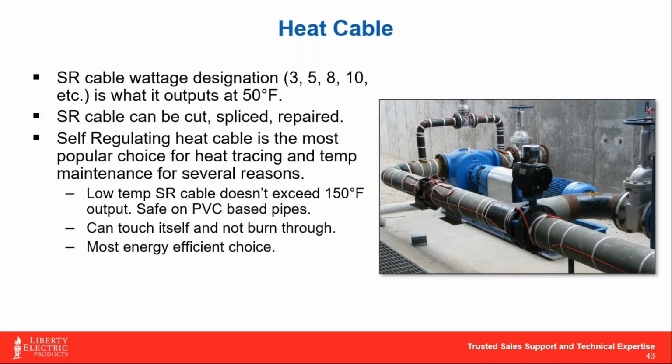But it is important to note that, in cases where you're using something like PVC piping because it's maybe just wastewater, you've got to be careful not to put too much heat on that PVC. Now, granted, the cable itself, like a low temp self-reg cable, will only work to a maximum of about 150 F. Oftentimes, if we double this up a little bit too much, it can be too much heat for the pipe, and over time it can disfigure it, and we just don't want that to happen.